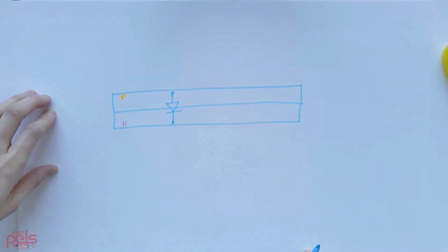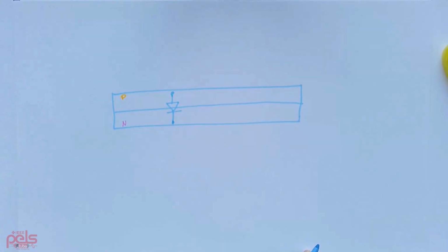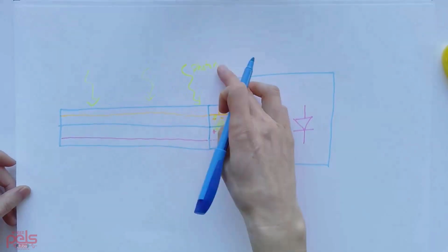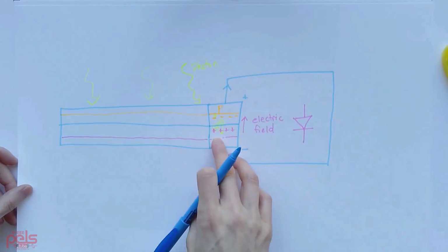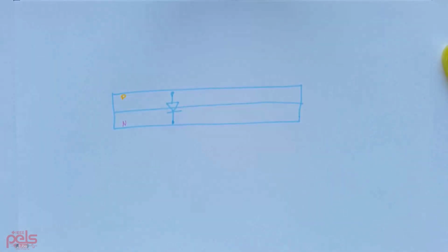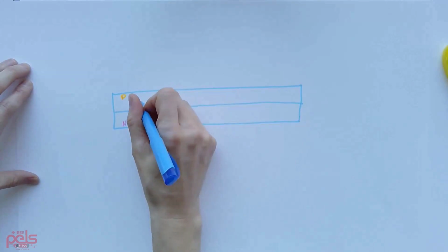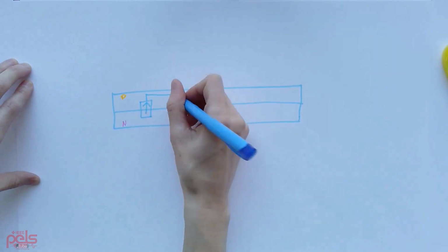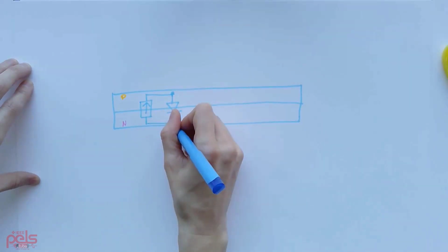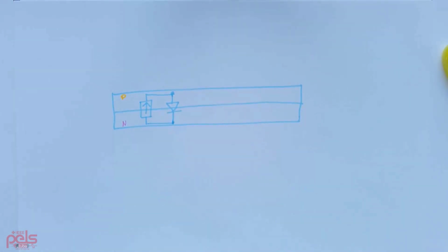And we also had the photoelectric effect. So the photoelectric effect, from when the photons were coming into the material, is creating a current actually that's coming out. So we model that as a current source. That's coming out here. Okay, so those are the two basic components that we use to model a photovoltaic cell.